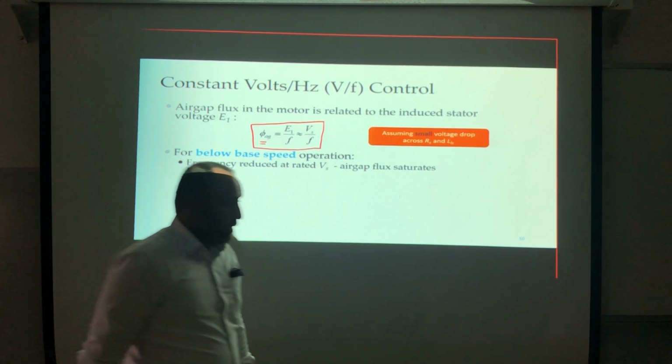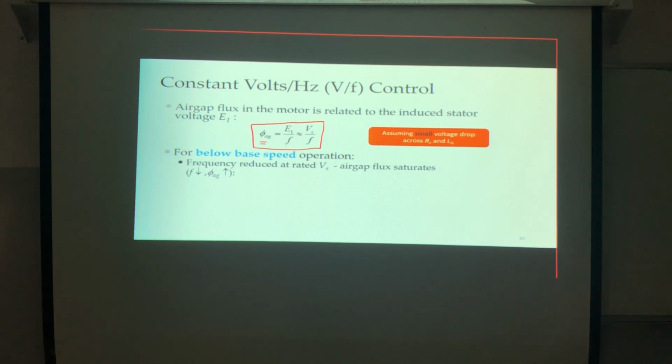Why? Now let's see. Do you remember the BH curve? Now the flux and current increase. The life is not easy like that. It's not a linear relation. So simply, if we recall the BH curve, or the I-lambda curve, we know that H is proportional to I, and B is proportional to the flux, correct? In the ideal case, I have a linear relation, but in real life it's not. What I will have is a nonlinear relation, which is saturated. Now, what will happen if you are increasing the flux?